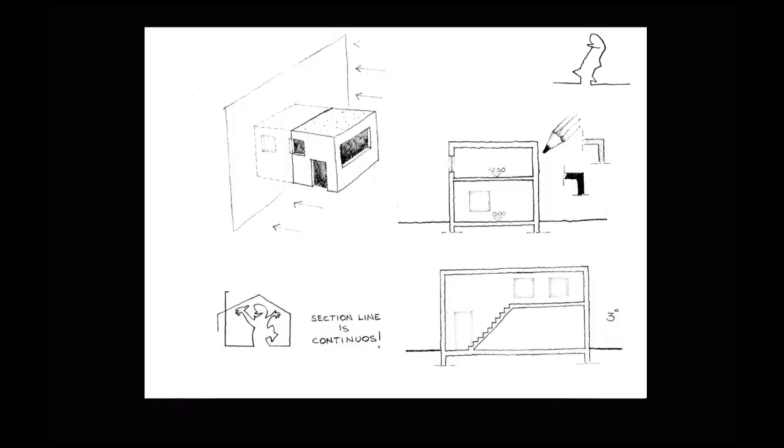Okay, so we're going to be drawing a section today, and just to give you a quick overrun, this slide just shows you the convention of a section cut. Over here we've got a three-dimensional mass of a building, and an imaginary plane dissects that building and represents for us in an abstract way, two-dimensionally, what's happening within the spaces in section.